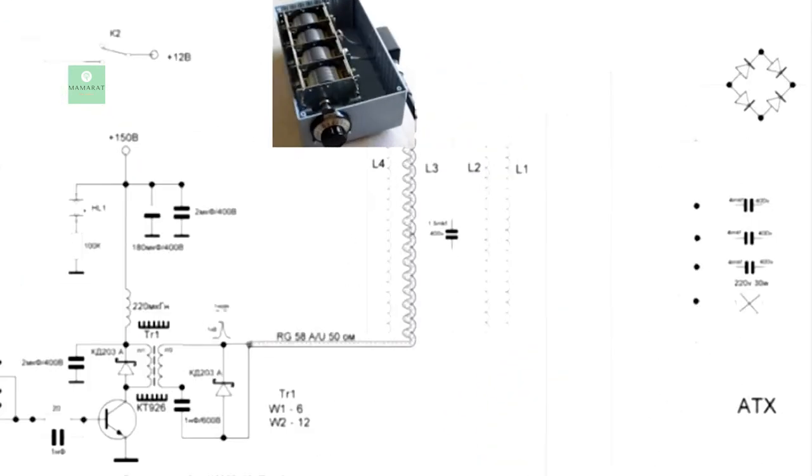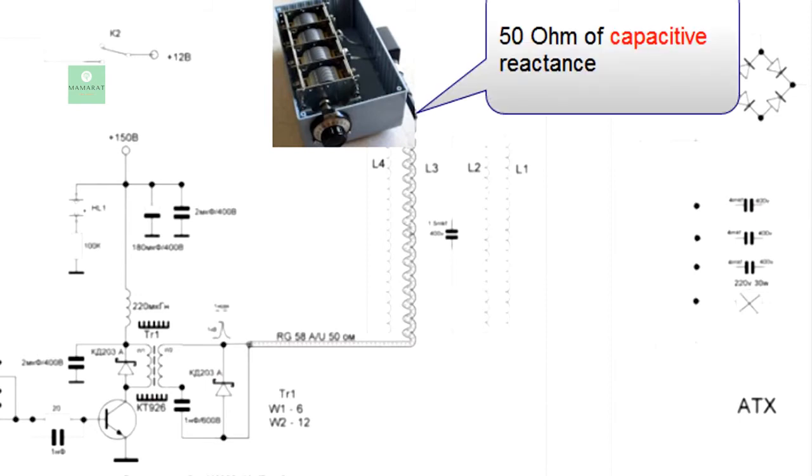I've got a sealed box at the end of the cable. It's got a good connector going into a sealed box. And inside the box is a thoroughly shielded, perfect variable capacitor. So in my frequency of operation of my signal generator, I've carefully adjusted that capacitor so it has exactly 50 ohms of capacitor reactance. So I got a 50 ohm capacitor at the end of a 50 ohm cable, and I asked each of these electronic engineers, am I going to get any standing wave ratio, or am I going to get any reflection of signal?